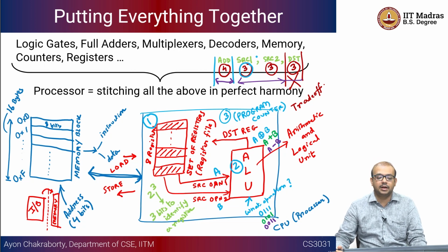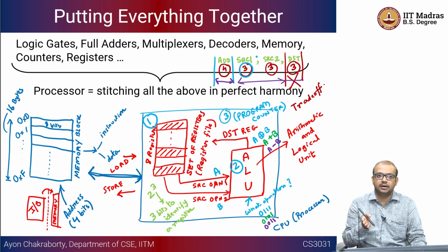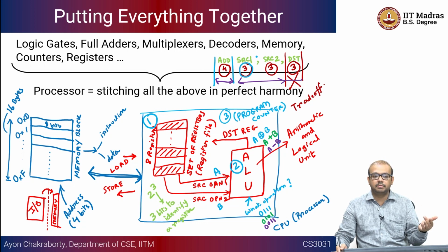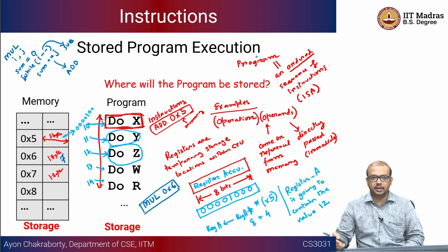As you can already see, the program counter is nothing but a counter, right. It is basically an up counter that starts at the location of the address where the program starts, and it keeps on incrementing, right. So you need to load the counter. Suppose your program starts from the memory location 10 as told in this example. So the program counter should be loaded with the value 10, or if 10 is in decimal, it should be 1010 for a 4-bit counter. Then 1011, 1100, and then 14, right, 1110. So as you can understand, it is basically an up counter which could be reset, which could be loaded with a particular value, and that is pretty much it, right.